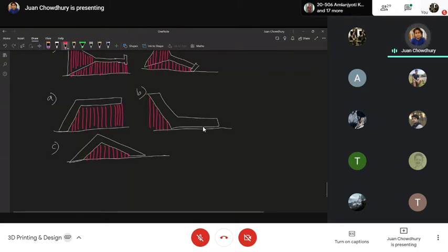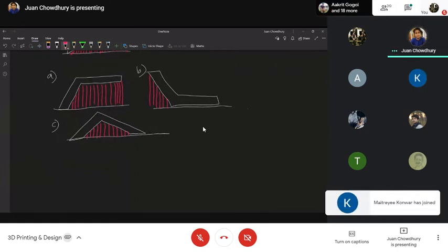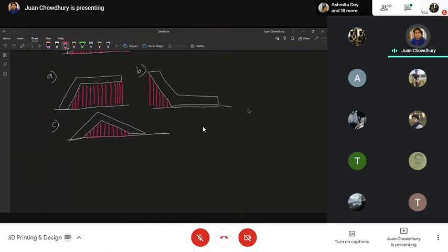Now, let's see how we can optimize support structures. What we really want to do with a support structure is to have a minimum contact area with the actual body. That is rule 1. Number 2, the point of designing a support structure is based upon the Euler cantilever beam, or Euler support structure, with its critical length.